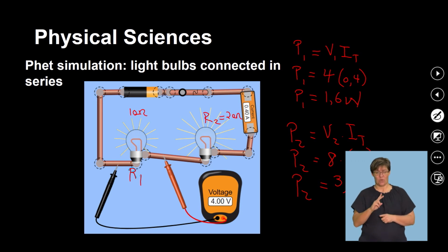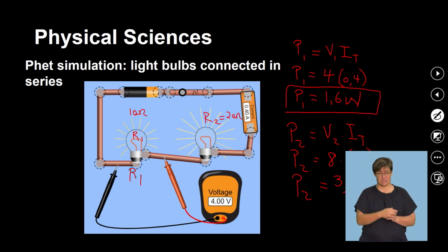So the power dissipated by a bigger resistor is greater if the same current passes through them. What distinguishes the quantities for R1 and R2 is that R1 is half the resistance of R2, while R2 is double the resistance of R1. This is a very important discovery, guys. It says to us that P2 is equal to 2P1.